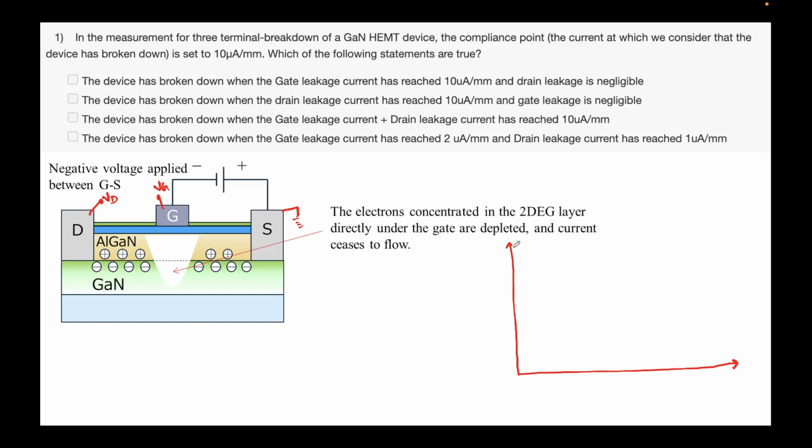I'm going to measure, and what is the thing that I'm going to change? So I put VG such that the electron gas is not there. So let's say VG is minus 5 volts. What I'll do is I'll sweep VD from, let's say, 1 to 100 volts. So on the x-axis I have VD. If the drain voltage is 0, there should be no current, even if you apply VG or don't apply VG, right? The current should not be there.